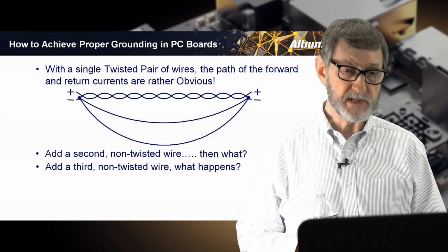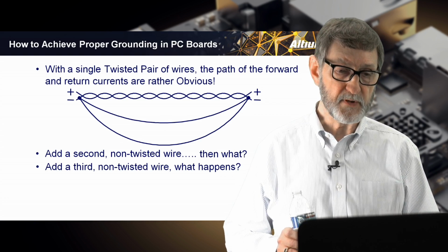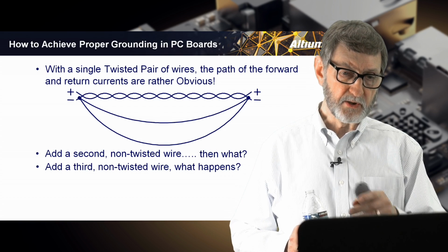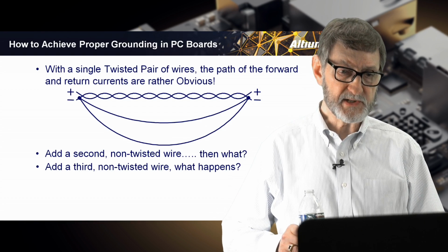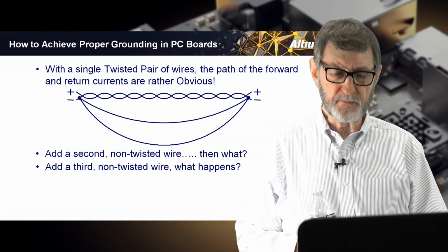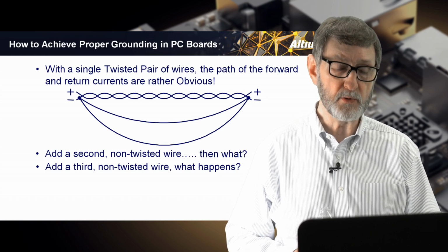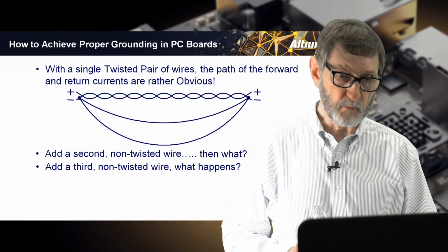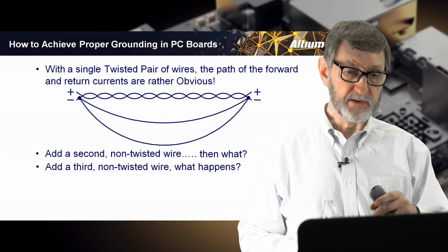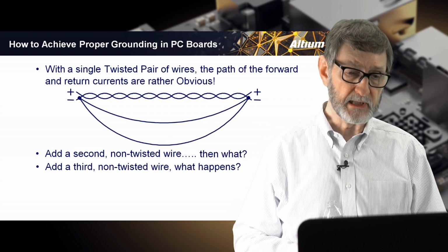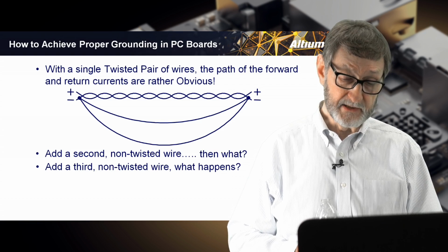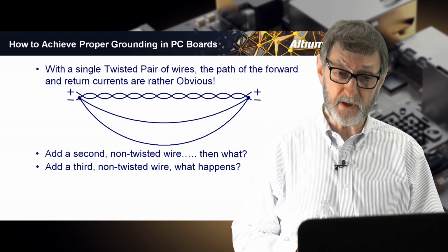As we increase the frequency and get to a few hundred cycles, the current in that bottom ground wire is going to lessen. And at some point, we're going to increase the frequency to the point where there's no current left in that bottom ground wire, and there will only be current in the twisted wire ground and in that second wire.